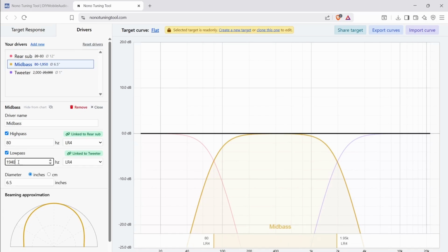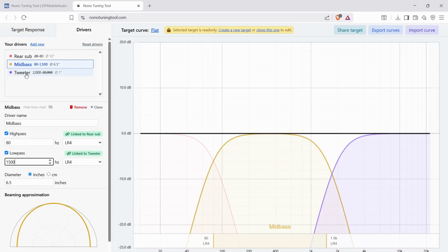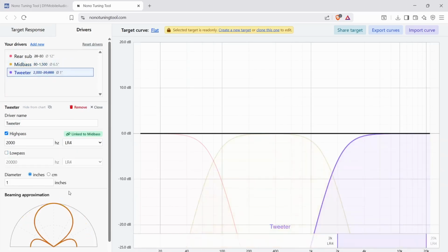And I'm just going to take this down and show the difference. So if you could get a tweeter to play, say, at 1500 hertz, the response is going to be stronger at that lower point with the 6.5-inch speaker. But it does depend on the tweeter. The tweeter size is definitely going to have an effect here, because obviously the bigger the tweeter is, the lower frequencies it can play, all else equal. If that were the case, you have a 1-inch tweeter, you can see that your on-axis response at 20K, it's pretty narrow, and that's expected.